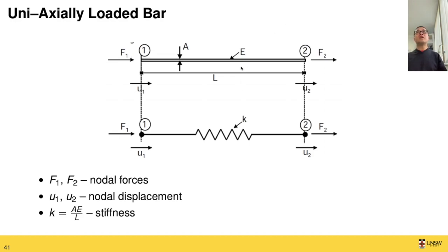The only thing that changed, as we saw in the previous slide, is that before, the spring has only a single spring constant K. Now we have a uniform cross section of the bar, which is A, a length which is L, and a Young's modulus which is E. In this case, the K value for the spring is replaced by the quotient AE over L, which governs the stiffness of the metal bar.